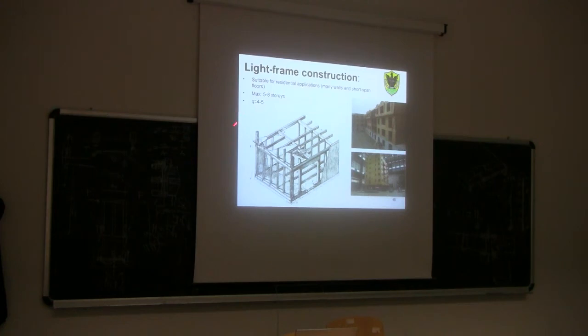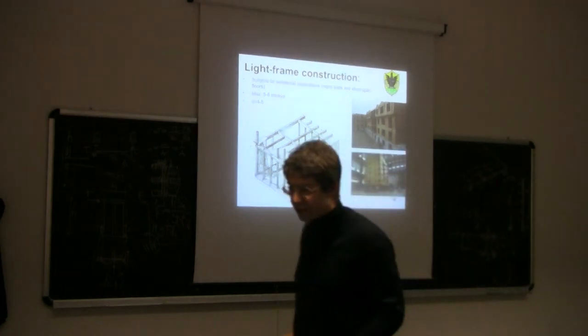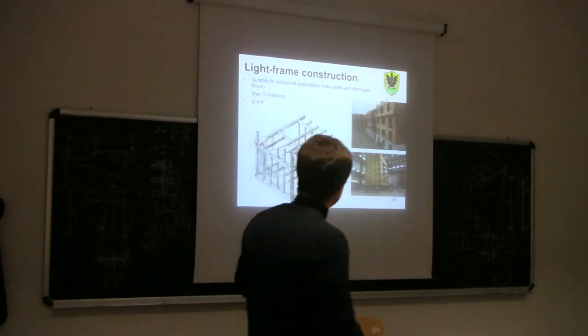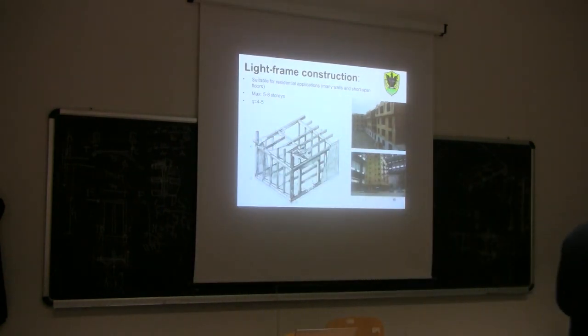Behavior factor, 4 to 5. According to the current Eurocode 8 and the Italian regulation, it is 5, but in the future revision, the Eurocode 8 will reduce it down to 4, because 5 is a bit too much.